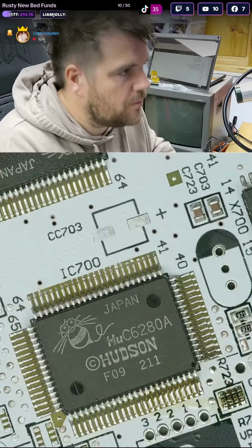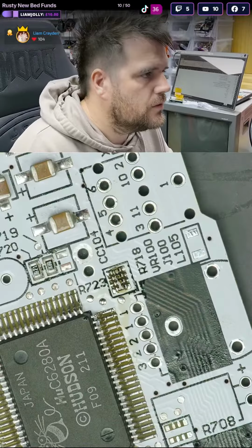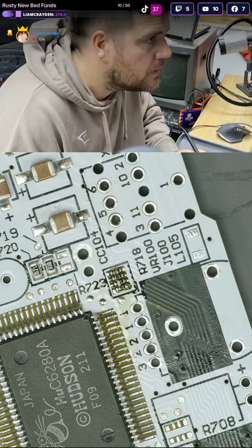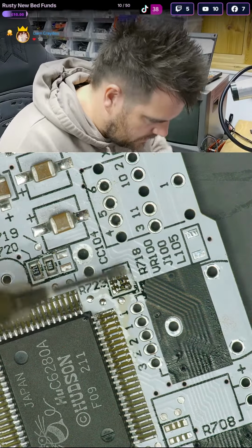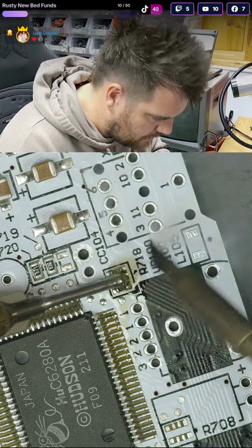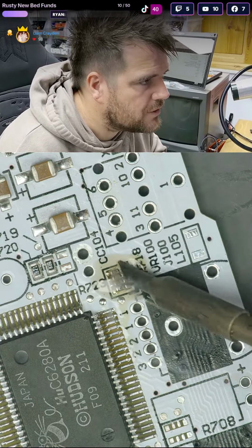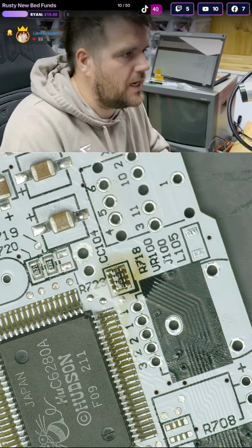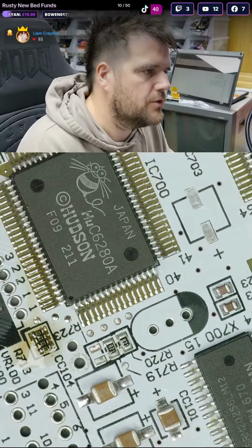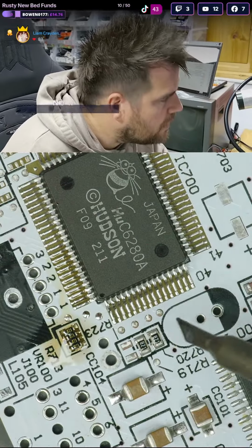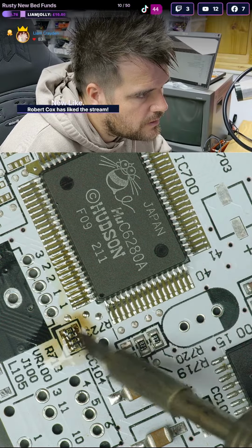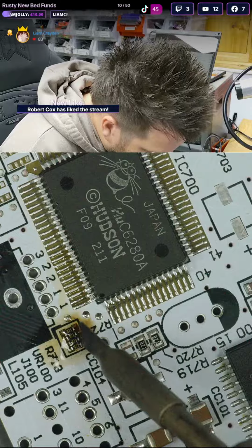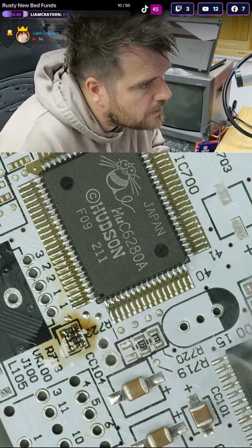I'll just tap up the corner resistor there. It's got barely any solder on. In fact, you could also clean the iron and just go down them, because they weren't well soldered on the original board, so they're not carrying much solder over to this board, so we'll just tap them up with the iron as well. Get a nice bead on there. That's it.